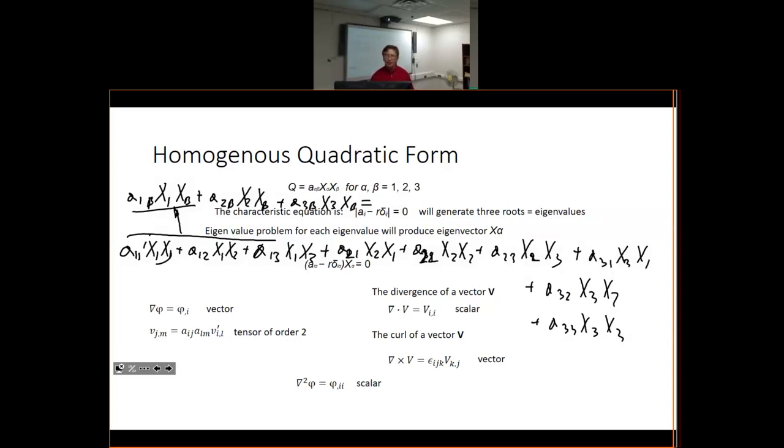You can produce the so-called eigenvalue problem, which means you can find roots of this quadratic formulation, and those would be three roots, and those three roots are called principal values of this function x. For the stress, it would be principal stresses.